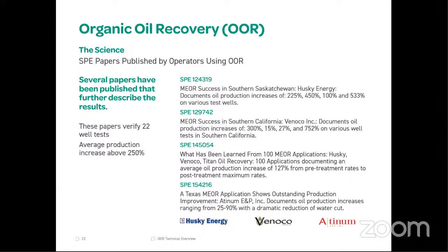So basically, for the residual oil, the droplet oil, these microbes go around it and can convert these droplets to micro droplets. And when it's converted to micro, they can easily move because there is no resistance force, and they can easily move with the water path to the wellbore side. So it's a very simple mechanism, nothing fancy, nothing rocket science, very simple. When the size of the oil droplet reduces, it can easily move. Fluid dynamics.